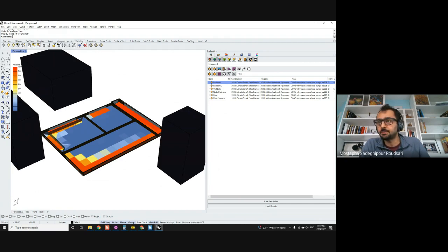Pedro has another question. Can I import any gbXML model from DesignBuilder to evaluate the simulation time in the cloud? Yes, Pedro, you can import gbXML into Rhino here and then try to run it. We don't support gbXML directly for a recipe, but you can bring it here, and when it comes in, it's a Honeybee model, a Pollination model that you can run. But it goes through gbXML, right? So you might need to set up some of the stuff that gets lost in the export-import process from DesignBuilder and bringing it back here to our Rhino plugin.